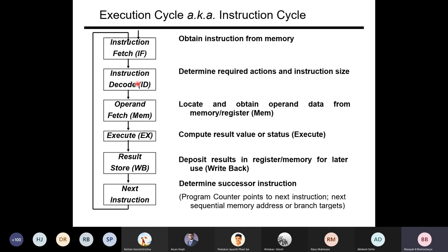because in every stage there are registers or memory elements. When you fetch the instruction from memory, you bring it to the processor side, but you need to hold that value, right? So there are some registers which are called instruction registers, which save the current instruction, because you have to save the current instruction until the operation of the instruction is finished, right? So in order to maintain those, you need several clock cycles which synchronize all transfer operations.